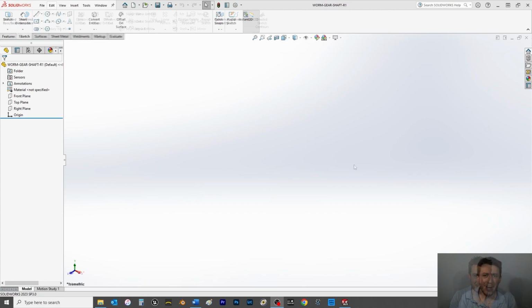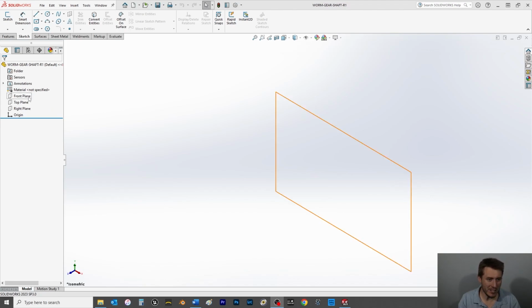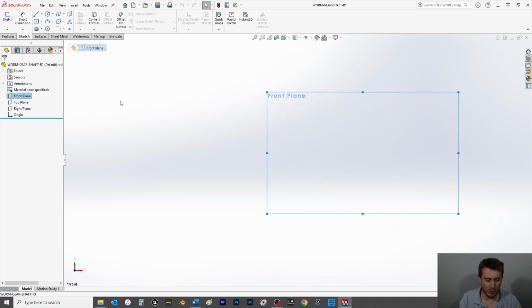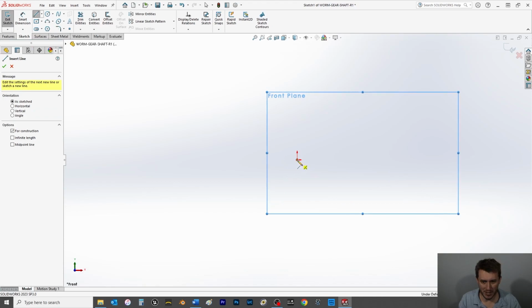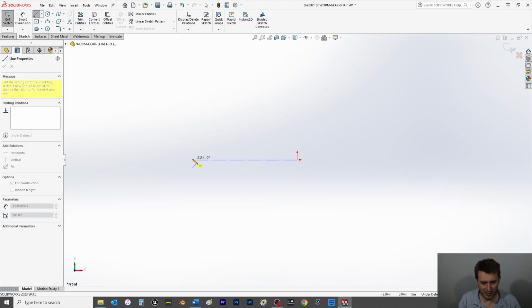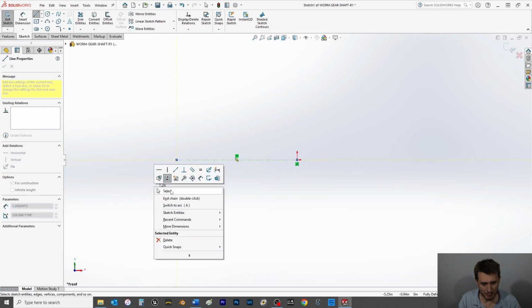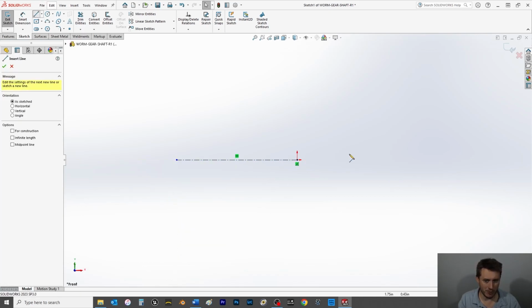Let's get started. Alright everyone, to start this part out, we're going to start on page 232, section 7.1. We're going to create the sketch profile for the Revolve Boss feature. So to start, select the front plane, hit Ctrl 8, then come up to the Sketch tab, choose a center line, click on the origin to make one end coincident, and drag out a horizontal line relation. Then we'll choose a regular line, and all lines will either be vertical or horizontal relation. We're just going to make the general sketch now, and then we're going to throw dimensions in and a relation.